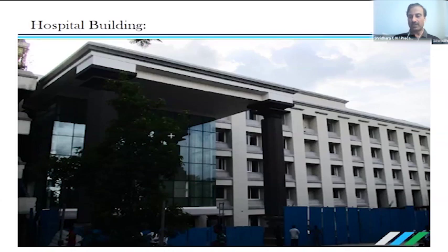Also, curing is not required for precast elements at site, because all elements are cured at the factory and brought to the site. This itself will save a lot of water wastage at the site. The precast technology will help a lot to minimize environmental pollution in the construction industry and also improve the construction